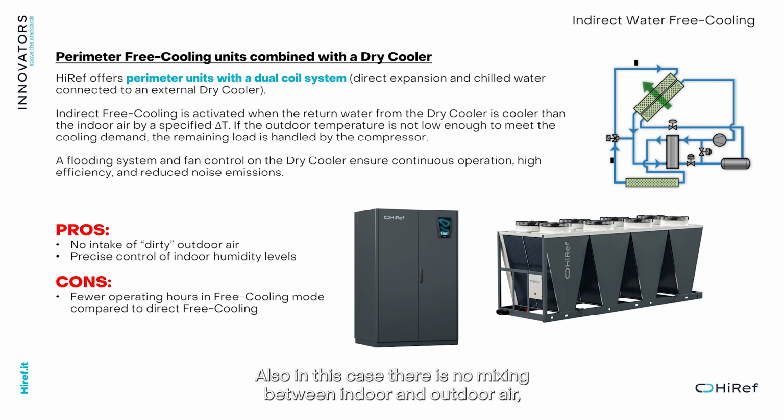Also in this case, there is no mixing between indoor and outdoor air, so there is no intake of dirty air. We have precise control of humidity inside the room, but the drawback is a reduction in free cooling operating hours compared to direct free cooling.